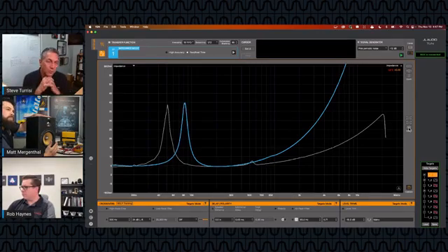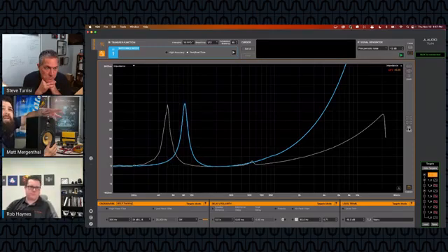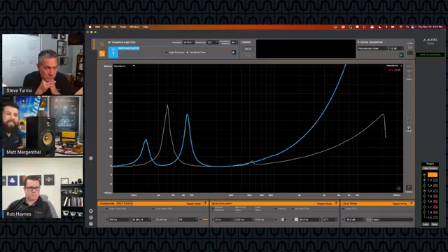So that's pretty cool. That's how, if you're trying to figure out the tuning frequency of a box, you put the woofer in the box, you do an impedance measurement, and you can find it out pretty quick. There's other ways to do it as well, but this is a pretty effective way. Right, and that's not the real Fs of the driver in free air. That's the sealed enclosure effect. Correct. So once you took it out of the enclosure, it would then change to whatever the free air specification would be. Indeed. All right, cool.